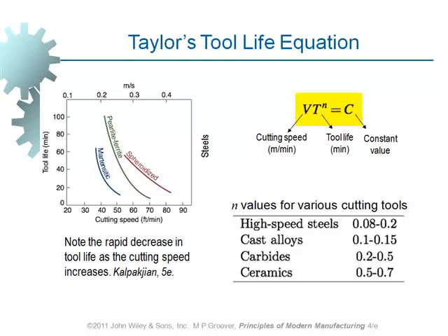And take a look at this slide before I move on. Tool life, cutting speed. It's telling you something. What is it telling you? You increase cutting speed if you want to lower the life of your cutting tool significantly. And also please note that if you increase this just a little bit, this will have a big impact on the life of the cutting tool.